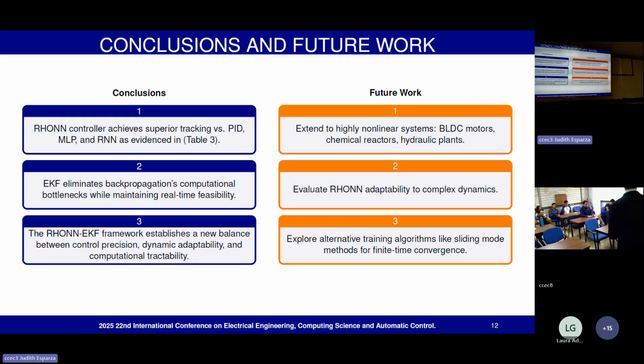If the motor overheats, it gets out of the linear region and starts to behave more like the nonlinear model. But that's why we are using the neural network, because it adapts online. So even if there are changes to the model, the neural network is still adapting to those changes.